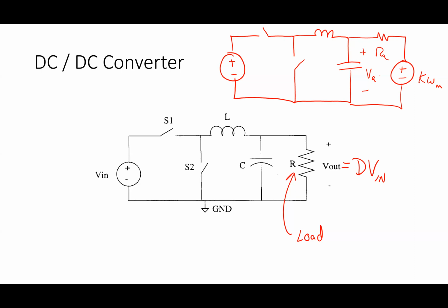And one of the things I said is, it used to be the case you didn't see synchronous motors. Synchronous motors are a hard thing to use because the torque it produces depends on this angle, and it's a very complicated little device. But with power electronics, it's very simple for me to start to control stuff, right? This is the simplest power electronics circuit you can get. There's a lot of details I'm leaving out here. S1 and S2 are not switches, right? They're transistors.